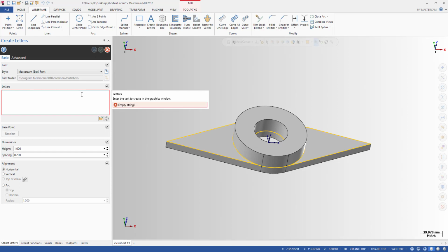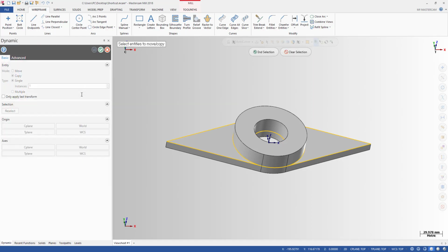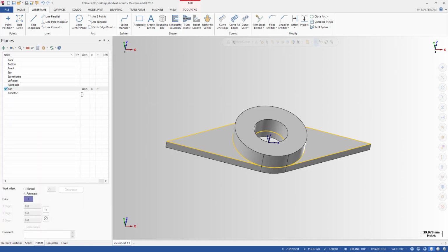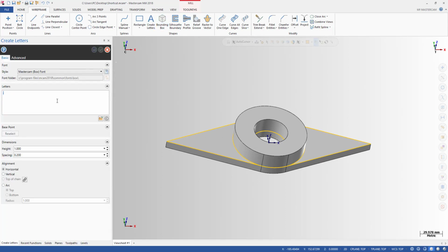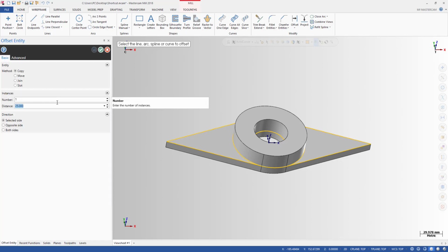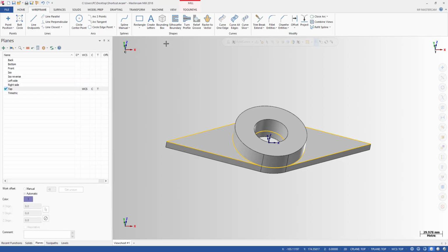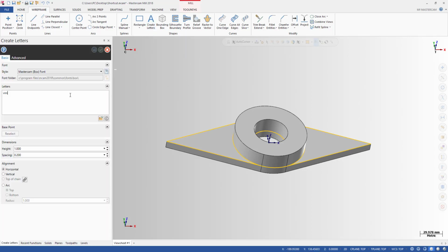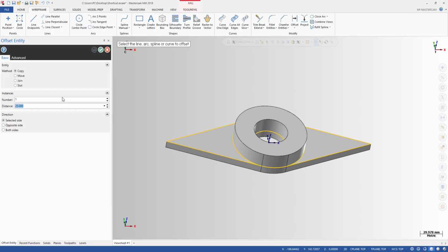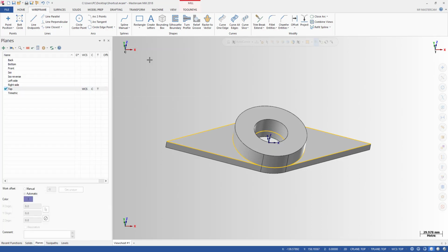You can see when I press a key that has not been set for a shortcut, it's no problem, like the V or the N or the R, the I. But when I press the O button, it closes the letter command and opens the offset command like this. You can see this is the problem we have when we're using shortcuts in Mastercam.